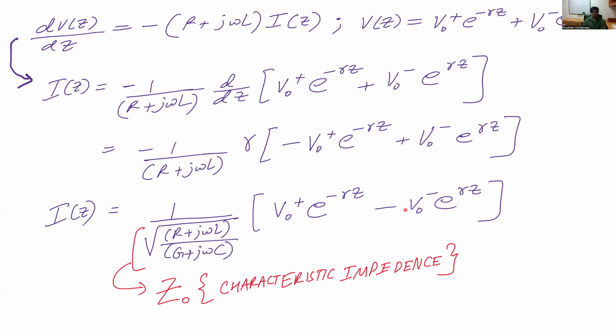What the negative sign actually denotes has to do with charge conservation, because if you work this out mathematically, if this negative sign was a positive sign, then you would actually have charge buildup in the transmission line. So the negative sign just says that the charge cannot build up at any location in the transmission line because the current is a continuous and steady current.